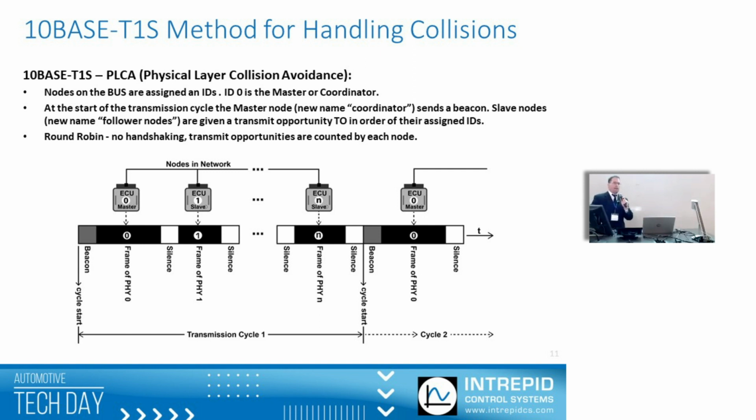In that case, you don't have to statically configure anything, right? So that's one of the advantages currently with CAN, CAN-FD, CAN-XL. You'll hear those guys saying, hey, we've got non-destructive arbitration, just remove nodes, add nodes that you want, and it just works. And that's been one of the big advantages of CAN, is you don't have to program a single node to know anything about any other node. It can be totally independent. In CAN, the only bad thing you've got to avoid is don't send the same ARB ID as some other node. That's pretty much all you have to worry about. But in 10BASE-T1S, you have to configure all the nodes to understand how many other nodes are on the network and node IDs and things like that currently. But there is topology discovery coming to eliminate this limitation or disadvantage relative to CAN-FD.